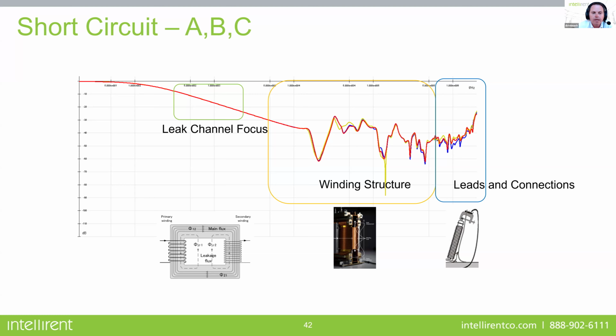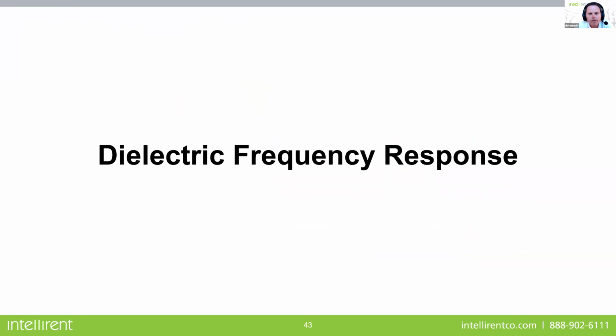It's pretty amazing to look at this, and then into your winding structure, leads, and connections. So again, we would do a phase-to-phase comparison. It's nice to have previous or benchmark results, but if there's a big problem, it will stick out. Now, a newer test that is performed is called dielectric frequency response.